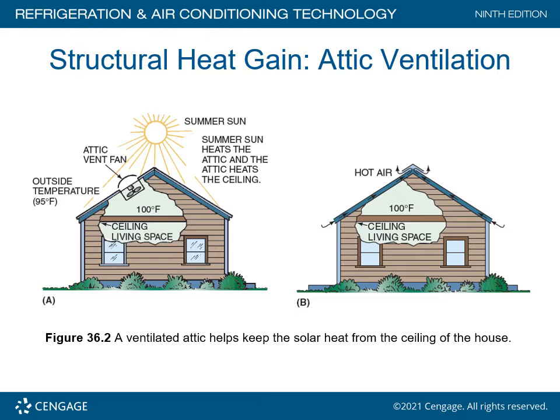Certainly helps, but in the grand scheme of things, I really think you have to pay attention to that heat that is trapped up in the attic on a hot day. And as an air conditioning expert, I can't tell you how many hot attics I've had to endure through the years, and I'm just very thankful that I'm still okay at this point in my life working in these hot attics. So basically, this figure says the ventilated attic keeps the solar heat from the ceiling of the house, which is a true statement if it's done correctly.